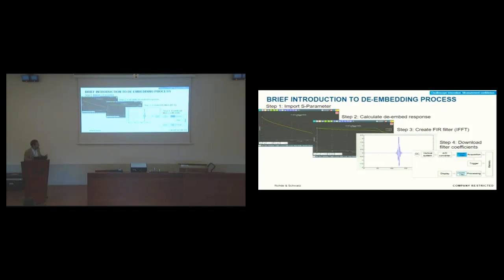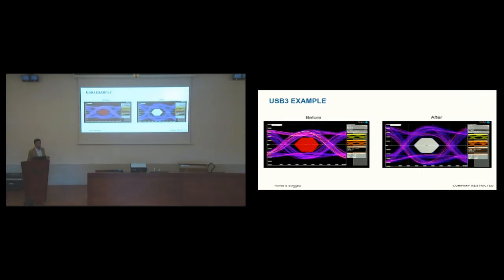And in this process is where the news are coming. The new things I'm going to tell you about today are really important. This could be the effect of de-embedding, for instance, before and after a USB 3 channel. You can see how the eye diagram is wider now, and it's fulfilling the standard mask.